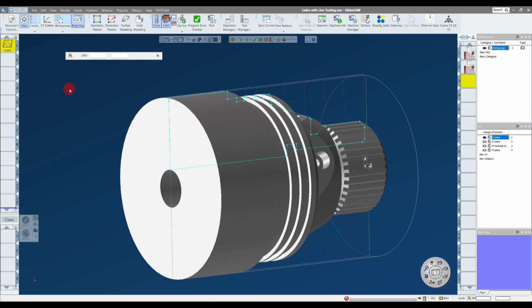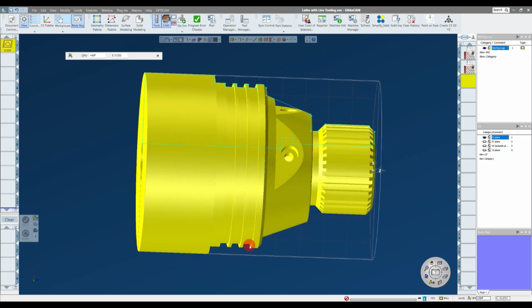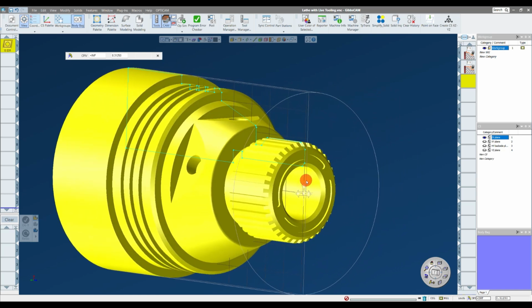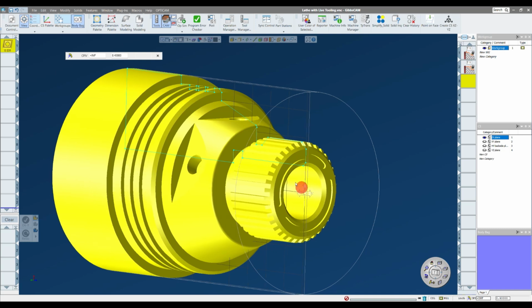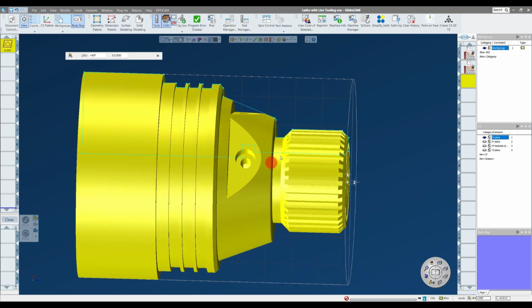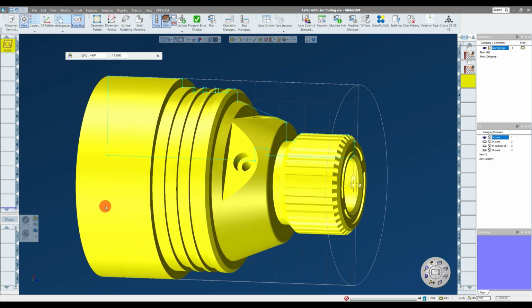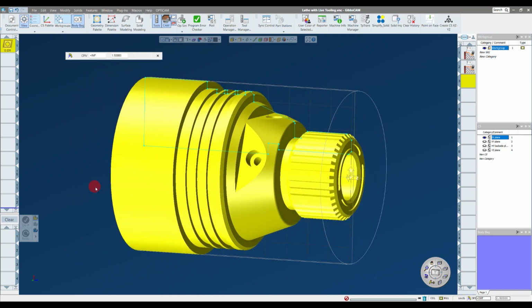You can measure thicknesses, and you can also check curves. So if I select my model and then click on that curve, you can see it gives me the radius of that through hole. And that's 0.3125, which means that the diameter of this through hole is 5/8 of an inch. And if I click on any of these diameters, it will give me the radius. So this neck diameter here is 5/8, and it tells me my stock has 1.5 inch radius there.